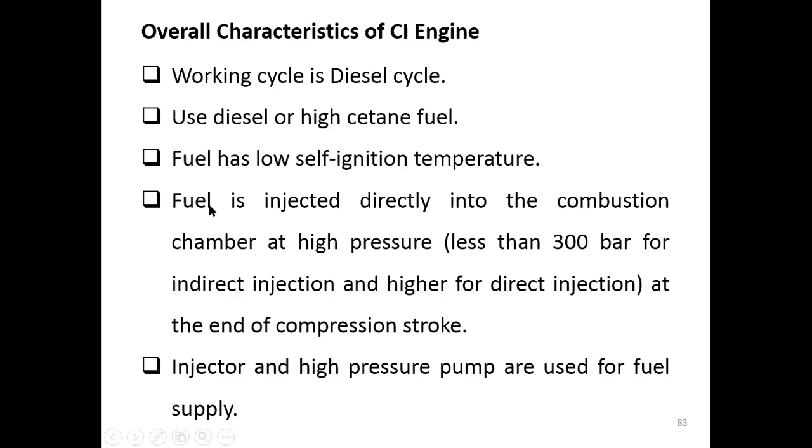Okay, the fuel is injected directly into the combustion chamber at high pressure. I put in the brackets just to remind you: less than 300 bar for indirect injection and higher for direct injection, right? So the fuel will not mix with the air.